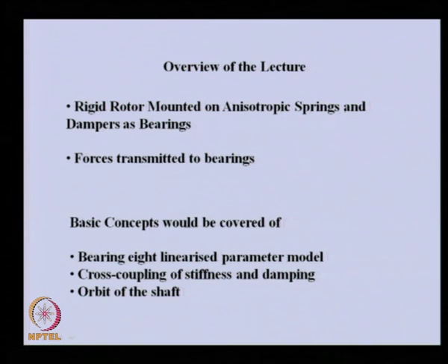We will even study the force transmitted through the bearing from the rotor. The concepts to be covered in this lecture are the bearing eight-coefficient linearized parameter model, cross-coupled stiffness and damping, and the orbit of the shaft.